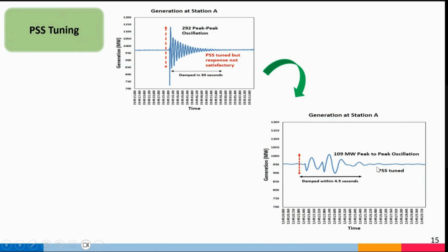As we have PMUs on most of the generating plants, either on the plant lines themselves or at the remote end of the power plant on those lines, if we sum all those, we can get the entire power plant, because we are trying to observe how the plant is responding completely. The power system stabilizer basically helps in damping of oscillation through excitation control. It is a supplementary control available with the excitation of the units.